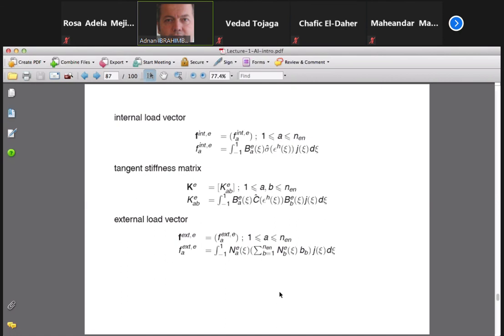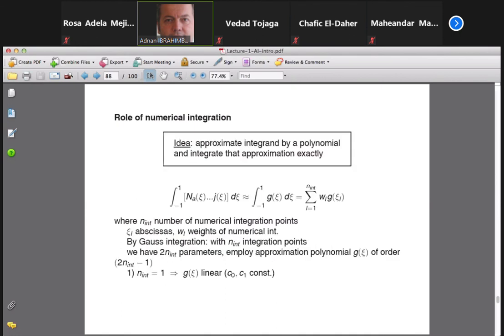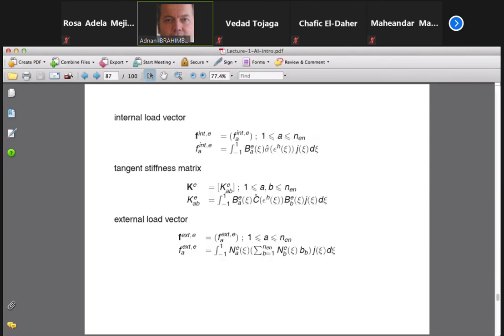In any case, the idea is that it is quite complicated for higher order approximation to obtain these integrals. Well, not overly complicated, but still complicated enough. And so the very good idea was not to compute them analytically, but to compute them numerically. And that's what I wanted to explain now for the remaining part. Namely, the idea goes as follows. Imagine now that first you're going to have these shape functions to compute, or any of these expressions. This is like a shape function or its derivative, let's say this one.